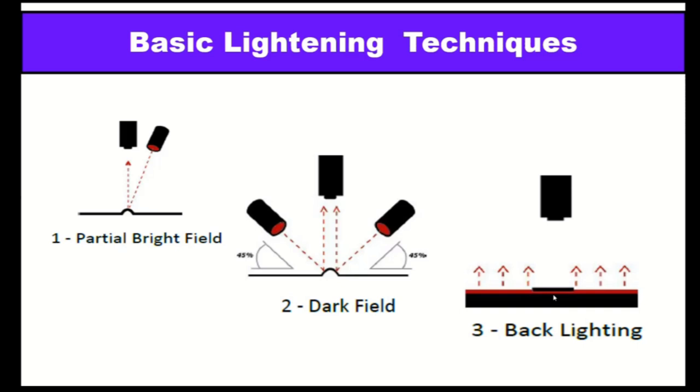Remember, polished jobs, polished surfaces, polished aluminum, polished steel: whenever we are dealing with such materials, there will be huge scattered reflection that can give a scattered view in the image. So you have to control that scattering by adding lighting sources such that some dark field will be created and shiny jobs can be correctly captured.